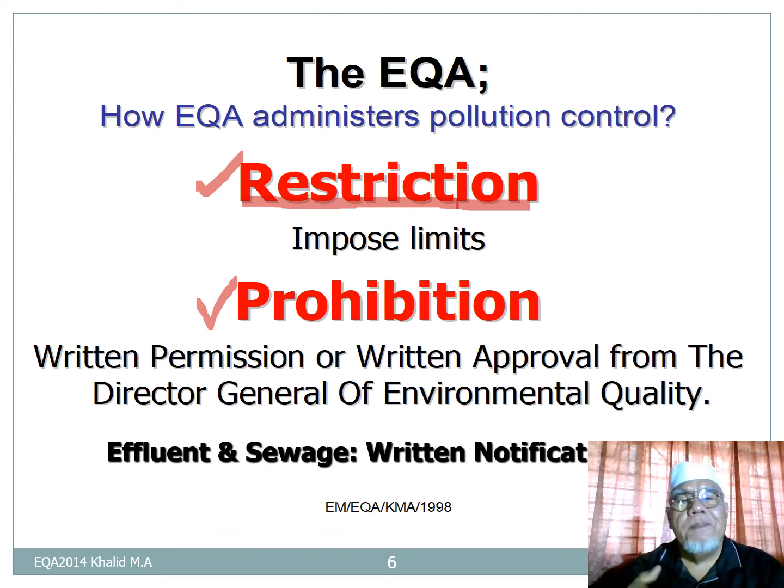Another example is perhaps, okay, we can discharge dark smoke, but not more than 20% opacity or Ringelmann number 1, meaning we are allowed to discharge dark smoke of any color, but not exceeding Ringelmann chart 1, Ringelmann is a German term, or 20% opacity. Correct me if I'm wrong. Those are in the clean air regulation. You can take a look. You can browse through this channel and take a look at CAR 2014. Just type that. You'll find the clean air regulations.